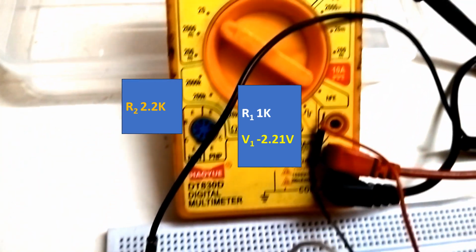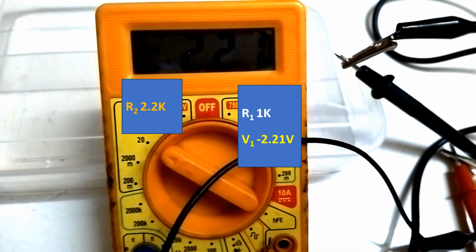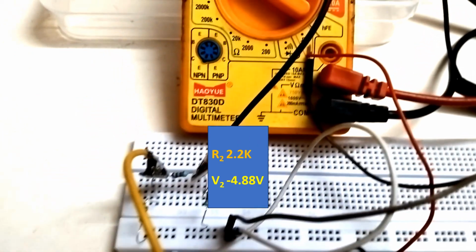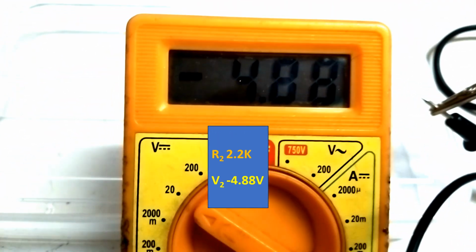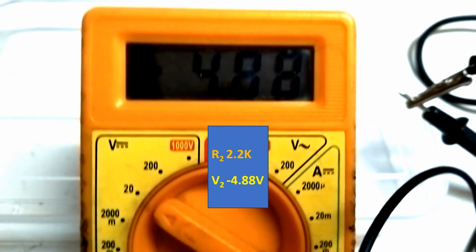Now I have changed the second resistor from 1 kilo ohm to 2.2 kilo ohms. So you can see that the potential difference across the first resistor, 1 kilo ohm, has come down to minus 2.21 volts. As expected, the potential difference across the second one is more than double. You can see minus 4.88 volts. That's because the same current is flowing through all resistors, and with the resistance more than doubled, you will have more than twice the potential difference across it.